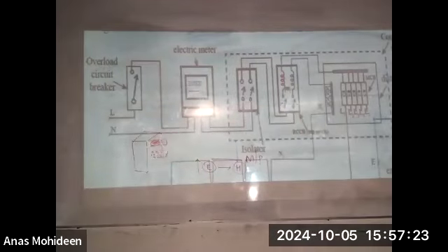Anyhow, now the MCBs are connected in such a way that you can organize and arrange the current supply towards the areas needed in your house. When you have a hall, kitchen, washroom, bedroom, you do have. Okay. So now, let's say you don't have the MCB connections. Then what happens? Whenever there is a power failure in an area, you don't know where the problem is. You have to check the whole house. This disadvantage you can overcome when you have the MCBs.